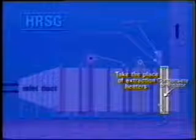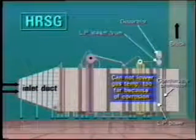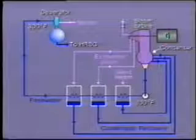In recent combined cycle installations, condensate preheaters are installed in the gas path downstream of the LP evaporator. These preheaters take the place of steam extraction heaters. This method has the advantage of utilizing heat from the exhaust gas. But we have to be careful not to lower the exhaust gas temperature too far because of the possibility of corrosion. So we may find in some installations a certain amount of steam extraction heating, plus some condensate preheating by exhaust gas. Now, let's see what happens in a de-aerator.